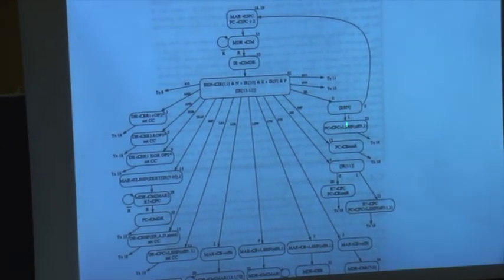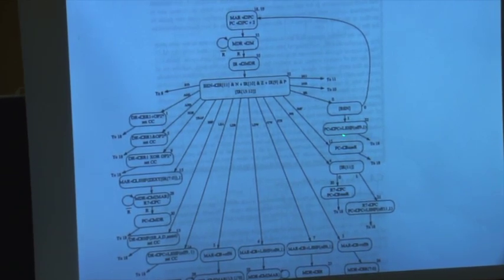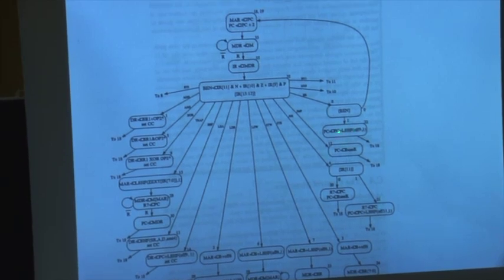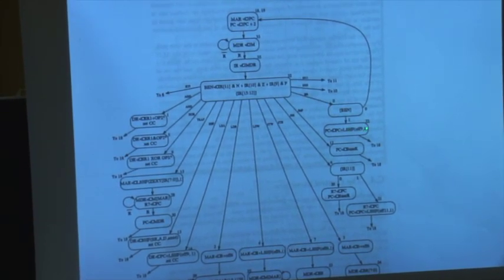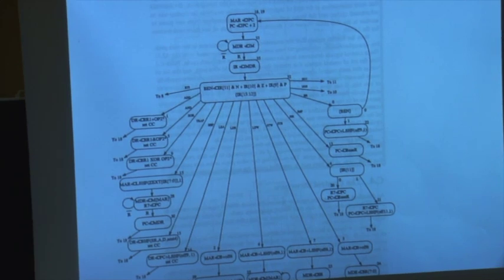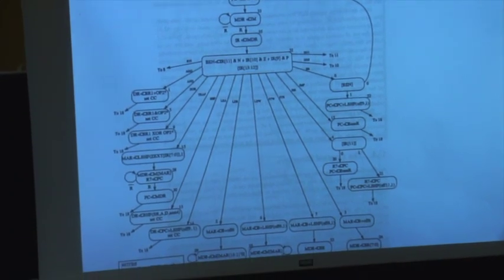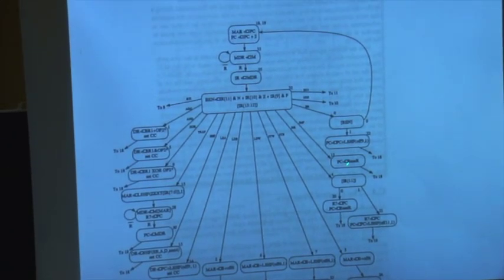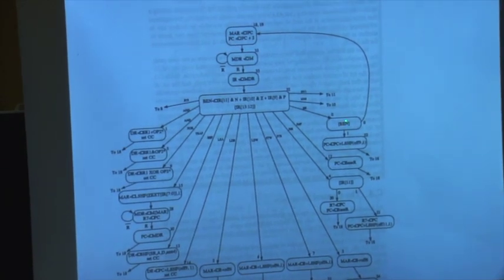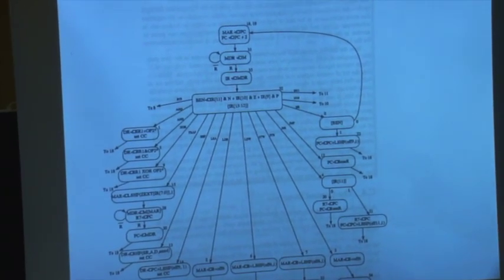If the branch enable is set to 1, then the next state computes the program counter based on the branch instruction, which is program counter plus the left-shifted 9-bit offset. Does that make sense? So this is how your branch enable bit determines what your next state is.